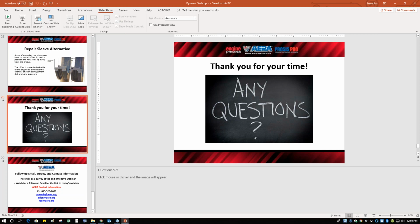Another one for you. Are there certain seals recommended for friction reduction or improved efficiency? Well, the latest design, Teflon, that really has improved the friction reduction with that Teflon coating. I would say that's the type of material or design that is greatly improved on friction reduction. But again, there may not be a Teflon lip version for the application you're talking about.